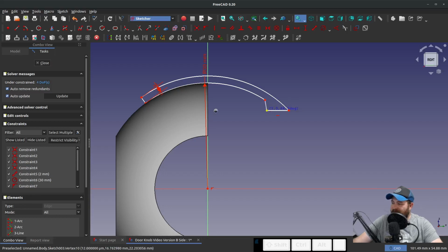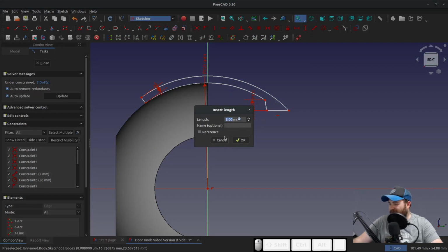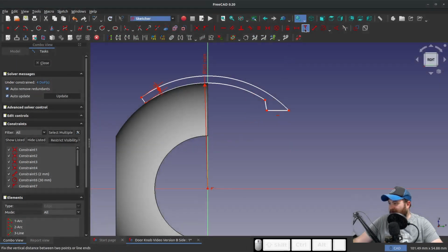And then here. And the question always is, what dimensions do you give a snap to get it working properly? I've made a lot of snaps, so I'm a little bit comfortable not doing the hard calculations. But if you wanted to do the hard calculations, you simply use strain in a beam. You find the max strain of your material, right, what your yield strain is.